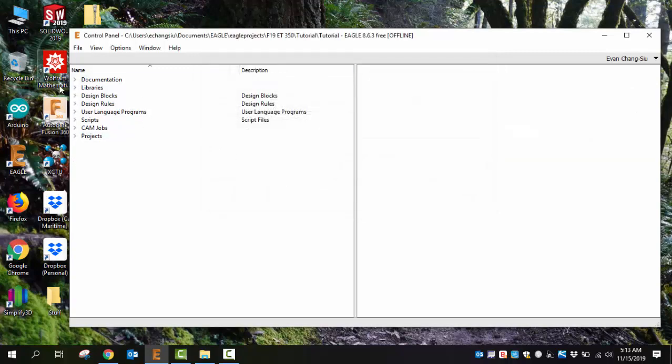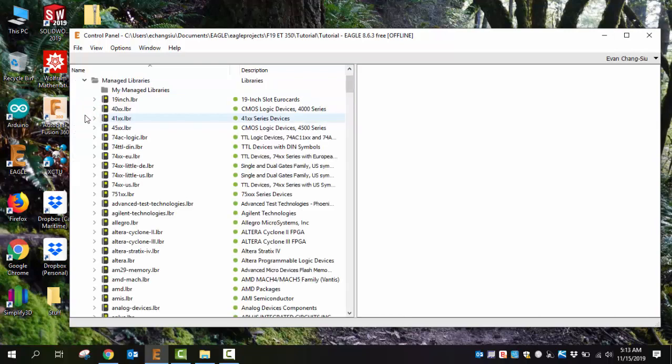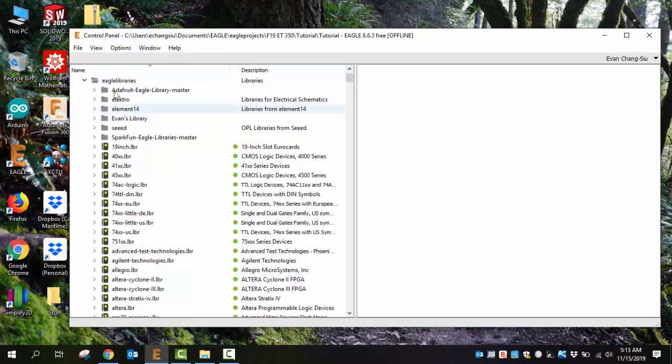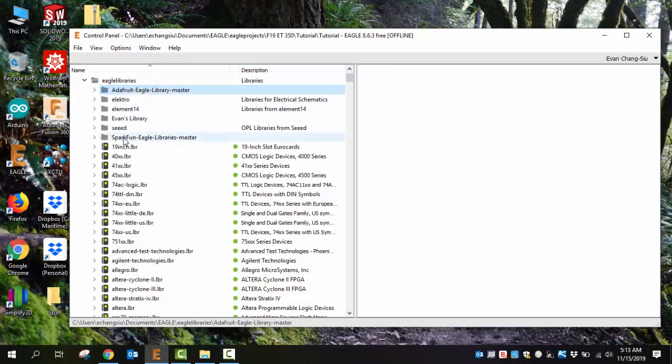And so let's say everything's set up. What you want to do, and I've forgotten to do this a few times, is go to use all. And here's the frustrating part about Eagle. You can't just go use all from up here, right? That sometimes doesn't cut it. You actually have to go to the sub folders and hit use all, use all, use all. Just make sure, right?